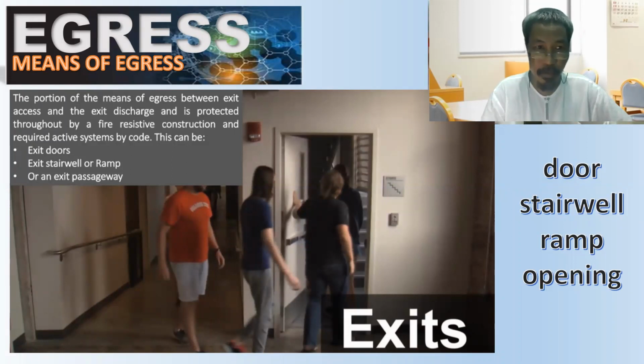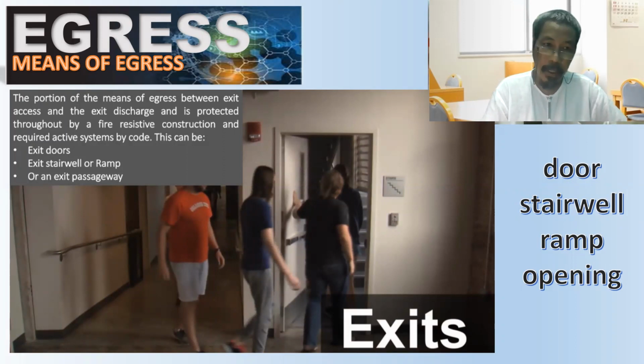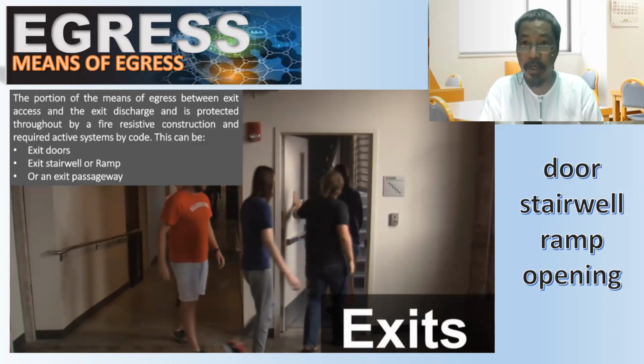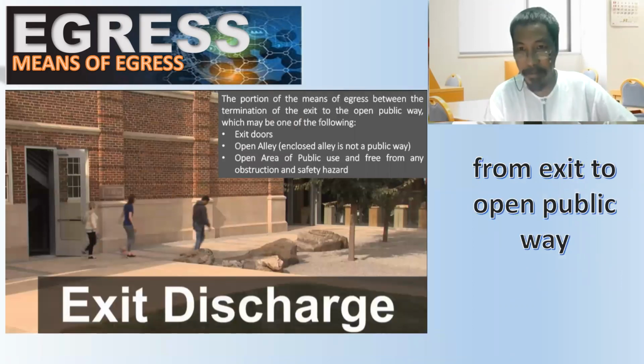So it is the portion between exit access and exit discharge, and is protected throughout by a fire-resistant construction and required active systems by the code. This could mean what? Exit doors, exit stairwell, or exit ramp, or exit passageway. So as you can see in this picture, this is exit door. An exit is meaning exit door. It is a door. It could be stairwell, could be ramp. It is an opening of a building going outside, right? Or specifically going to exit discharge, right?